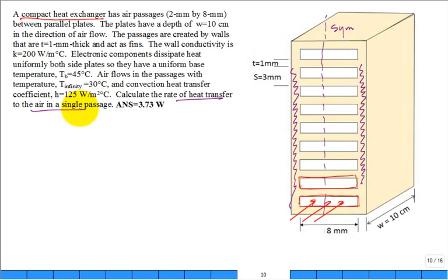And the challenge is just you say, I know the temperature at this part of the passage, but what's the temperature kind of out in this part of the passage? Isn't it lower? Because that's not where the heat source is. The heat source is over here and over here. So isn't it going to be a little cooler out in this part? Because doesn't it have to conduct and then it's convecting? So guess what? There's my fin. You just discovered a fin in a compact heat exchanger.